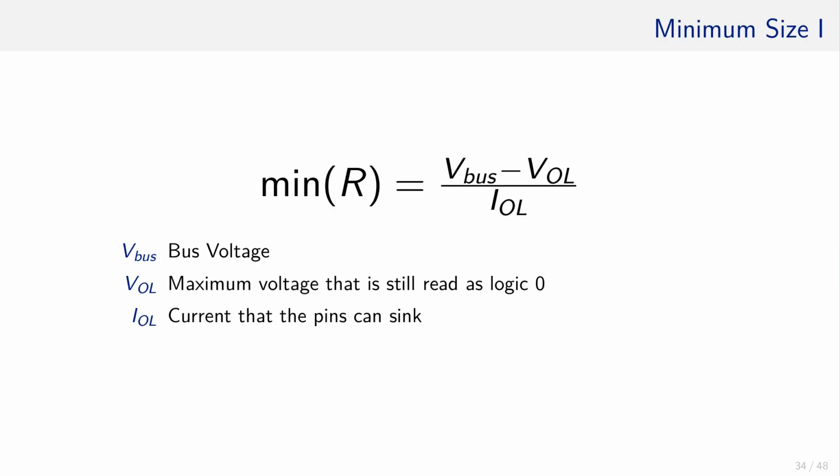If the bus is connected to the ground, a current flows from the source through the pull-up resistor, through the bus wires and the device into the ground. There is a limit on the current that can be handled by the pin. IOL describes the maximum current that can go through that pin to pull the bus wire down to 0 and hold it there.